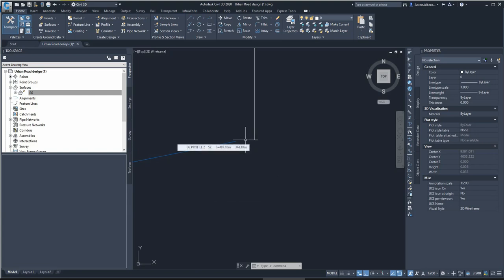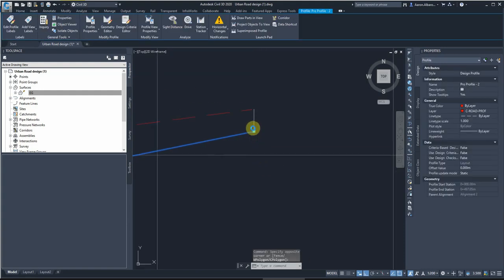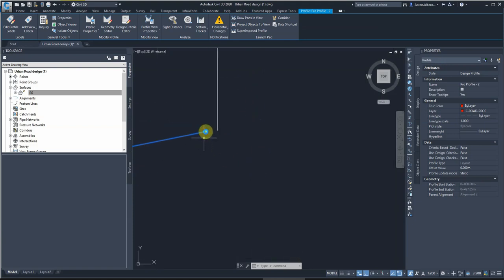If you look at your corridor, you see a large drop down. That means part of your alignment doesn't have any information of height, so it goes to 0. To avoid that, just make sure it's either sitting on this point or at a vertical line of that point. So I'll just make it sit here, because we'll need it to be slightly below for the intersection design.